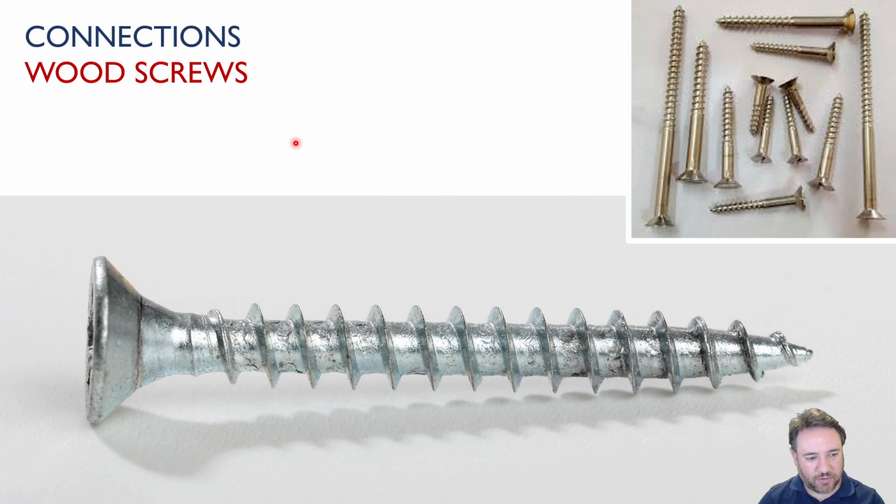But one of the primary things in the shear behavior is that the sheathing connected to the studs needs to move laterally relative to each other when the wall deforms. And screws are not so good for that because they don't have that kind of inelastic capacity in shear movement. But they are very good if you need withdrawal strength.